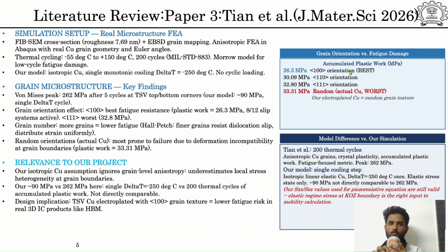Now coming to the model comparison box, which is here: model difference versus our simulation. Their model considers anisotropic copper grains, crystal plasticity and thermal cycling, which result in higher stress values. But our model uses isotropic copper and single cooling steps. So our stress is around 90 megapascal, which is lower.